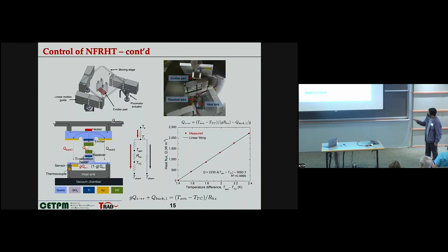without applying the calibration heaters. So whatever the heat transfer from the emitter to the receiver will eventually pass through these calibration heater regions, so that the heat transfer rate QE from the emitter to the receiver here, and the generated calibration heat generation at this point, we assume that they act the same way. That's the basic assumption of this calibration.